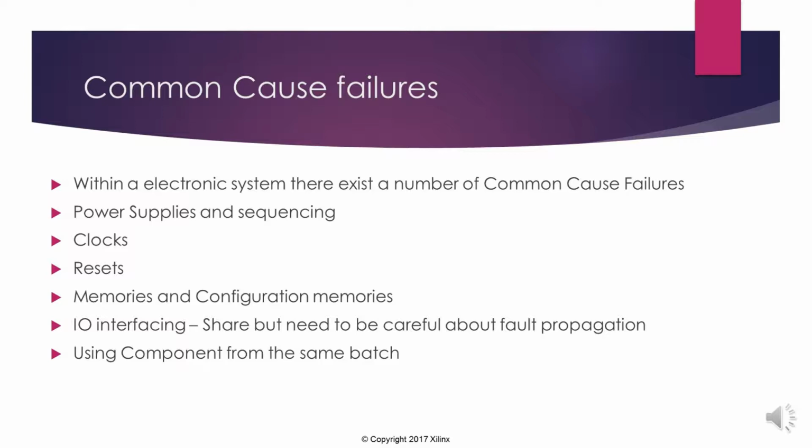Now I/O interfacing becomes difficult because you need to ensure that a failure can't propagate from one module to the other module using that interface, or that the failed module can't take out that input and prevent it from being used further. What's used in some areas is diversity of components as well, in that you will use components from different batches in case there's a manufacturing impact with that batch, or maybe you'll even use devices from different sources, or different manufacturers, or completely different technologies to implement those redundancies.